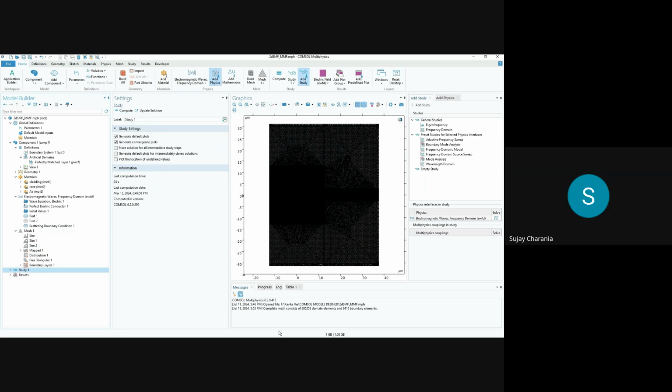Just a comment, I don't know the particulars of Kavita's design, but the multi-mode fiber at 1550 nanometer with a typical core cladding refractive index and with 15 micrometer core radius would lead to a V number of about 10, and the number of modes would be approximately 100.